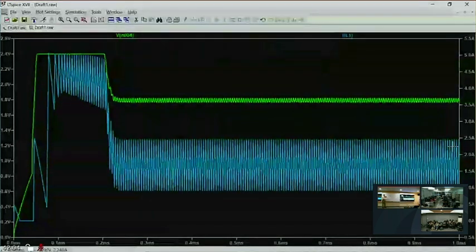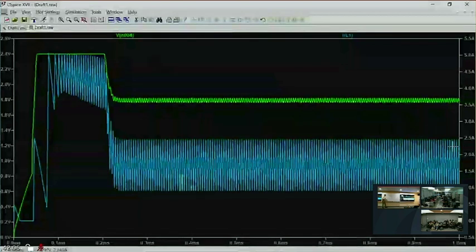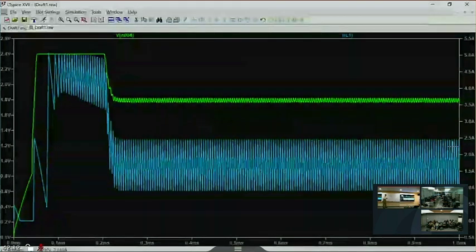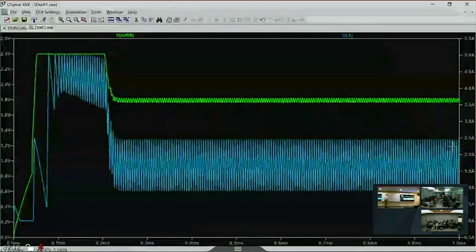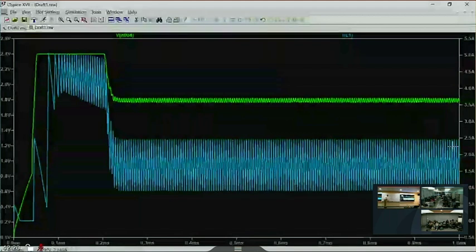So what's connected to the S pin will be the same. Somehow we have to reset it by a different quantity. Instead of resetting it by inductor current, we'll modify it by a slightly different thing. The clock will put out two waveforms. One will be a slope function, which is where slope compensation gets its name. And we'll add some of that to the inductor waveform.